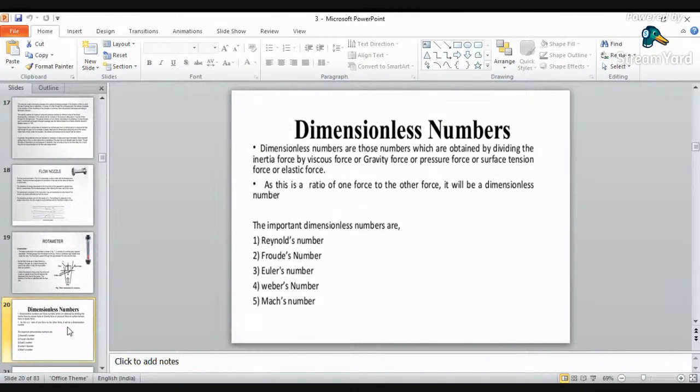The next topic is dimensionless quantities, or dimensionless numbers. Now see, what are dimensionless numbers first of all? As the name itself suggests, these are numbers or values which do not have a dimension. It means they must be ratios of the same quantity, right? When we divide the same quantity, only then it becomes a dimensionless quantity. Dimensionless quantities or numbers reduce the number of variables that describe a system, thereby reducing the total amount of experimental data required to correlate physical phenomena to a scalable system.